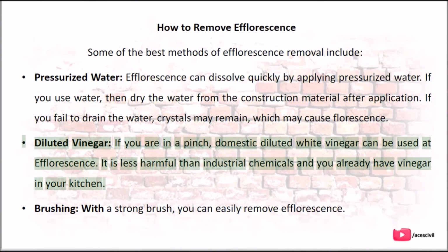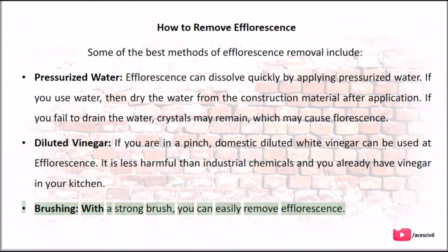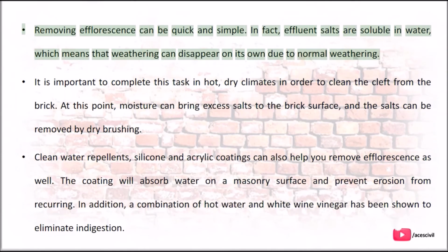Diluted vinegar. If you are in a pinch, domestic diluted white vinegar can be used on efflorescence. It is less harmful than industrial chemicals and you already have vinegar in your kitchen. Brushing. With a strong brush, you can easily remove efflorescence. Removing efflorescence can be quick and simple.